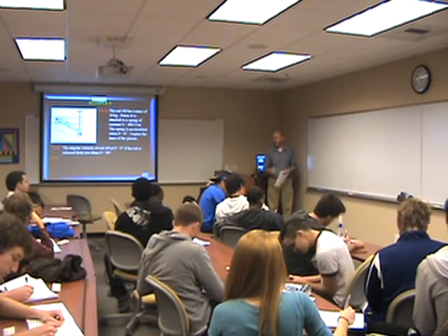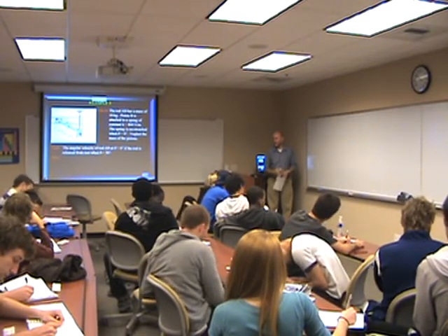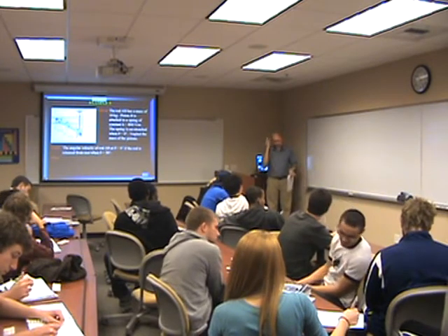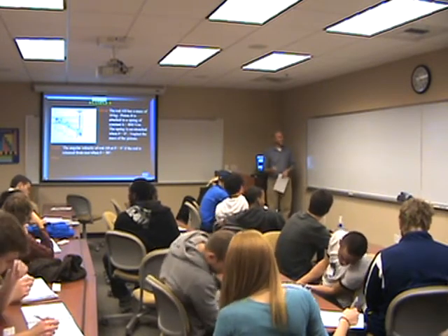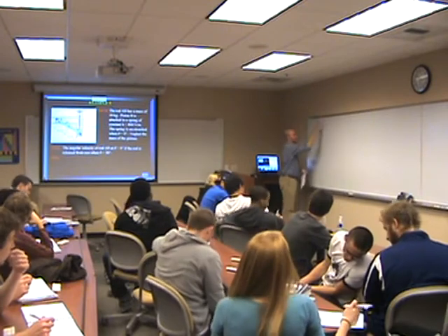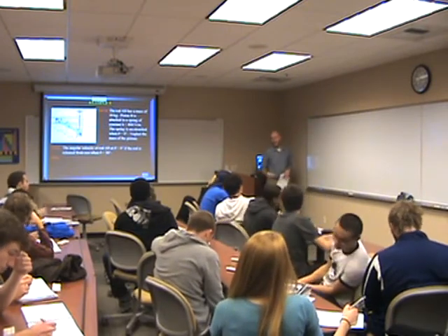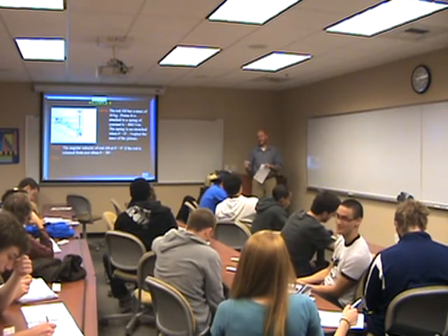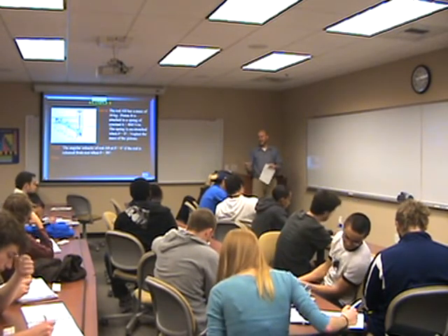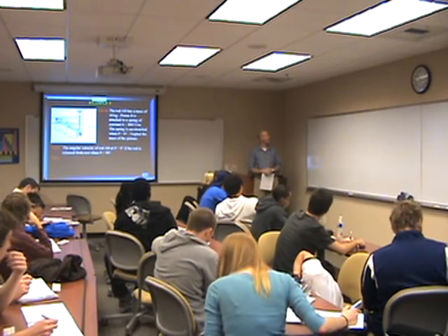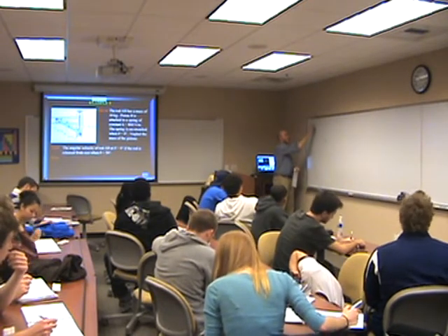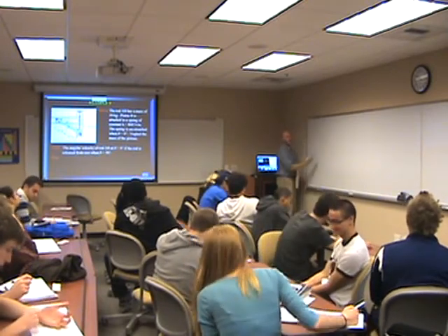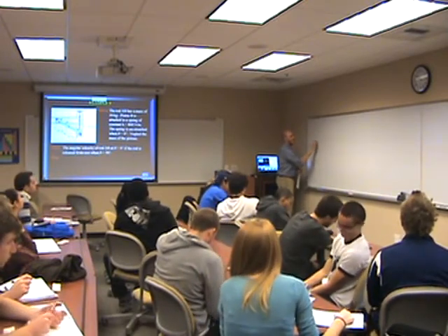You'll probably not need a formula sheet for this because you've been using it. Is that rotating around the ends or is it in the middle? Where is it rotating about? About the instant center. Where is the instant center? It's either up or down from A because it's perpendicular to the way A is going, and it's also perpendicular to the way B is going.